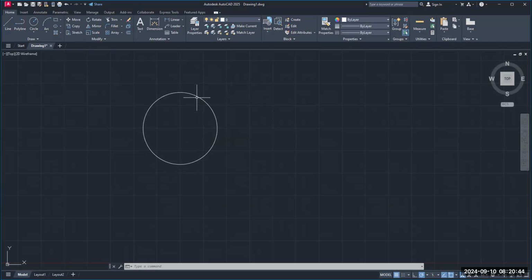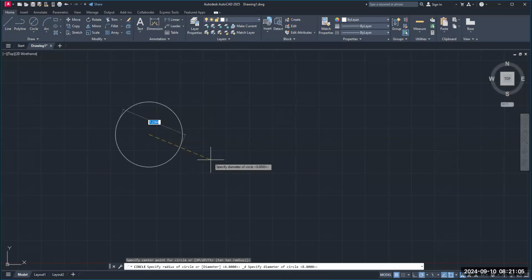I'm going to click here. Look, this time I'm going to click on the circle. Just click on it and hit the delete button. Now we're going to draw a circle again. Get a circle, go to center diameter, and we're going to click. Now, this time, I'm not doing radius, I'm doing the diameter dimension, right? So the diameter is twice the radius. So I'm going to type in 8 this time, enter.